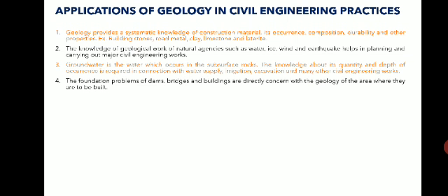And you must know the rocks which surround the catchment area, right? Because we construct a dam for storing water in the reservoir. The water flows over a long distance and comes into your dam site, and the catchment area is the surrounding area over which the water flows and comes to your dam, and gets accumulated in the reservoir. Suppose those rocks are not strong, if they are weak, then what happens? Because of the force of water and chemical reaction with the water, rock may dissolve, undergo weathering and erosion, and all the rocks get dissolved and accumulate in the dam.